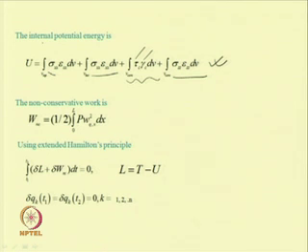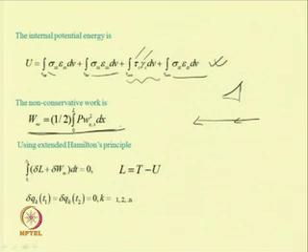Now, as an axial load is applied to the system, one can consider a small deformation of the system, taking the inextensibility condition. One can write the work done due to this load equal to half integral 0 to L of P into (del w by del x) whole square. In this way one can find the non-conservative work done and also the potential energy and the kinetic energy.